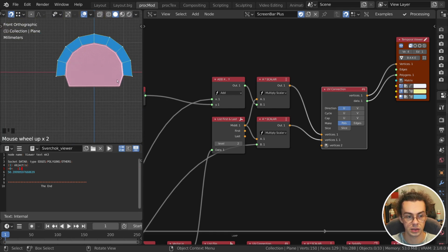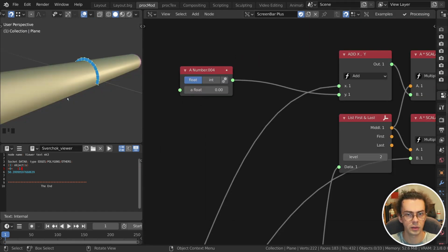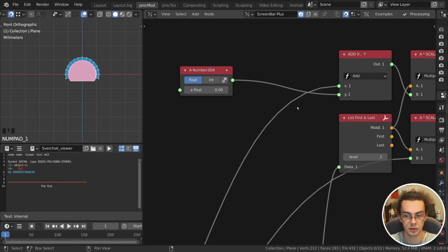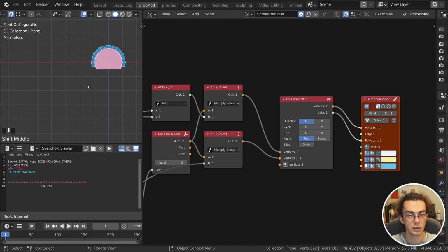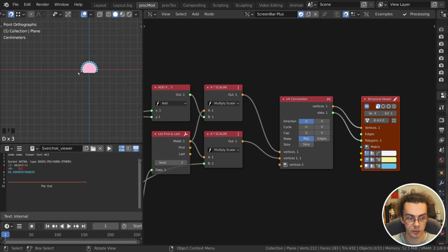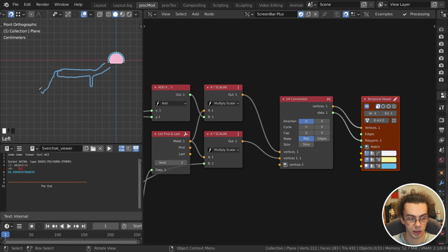I'm just going to increase the resolution here because at the moment this actually wouldn't hold. So for now we're going to work entirely on profile, and then we're going to extrude it back just how we did with the lamp. So staying in side view here, what I want to do is create my profile parametric. And the shape of this is kind of down and then along. So this is the first one. It has a little overhang at the front as a clip, and then it comes back up here. And then we also have a second piece, and it's going to come down like this, have a circle at the end, and come back up.